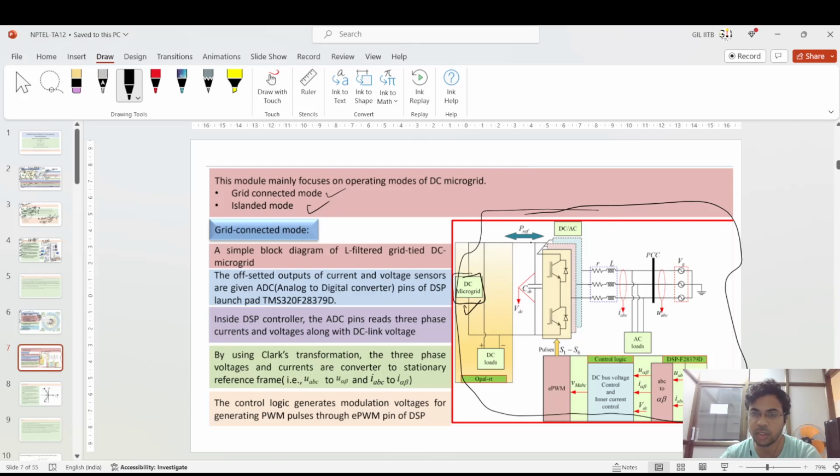Suppose you have a DC microgrid generating sources, you should connect them to this DC bus bar, that is a capacitor if you could see. This is for ripple reduction, and you can also use DC loads directly connected to this DC bus bar. And for laboratory experimentation, this whole DC setup will be in the OpenRT. I told you in the previous lecture that this is the RTDS, real-time digital simulator, which synchronizes with the real-time clock generating system.